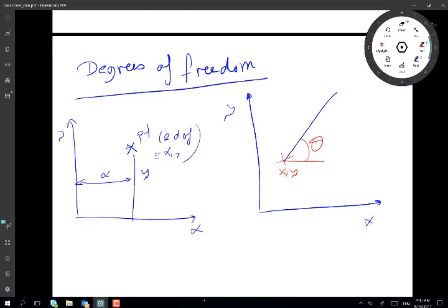What we're interested in is the distance from one joint to another, which is a line. So the line replaces the link, irrespective of the shape. Now this link in the linkage, at this point in time, is just floating in a plane, and it has 3 degrees of freedom, being x, y of a point, and the angle theta.